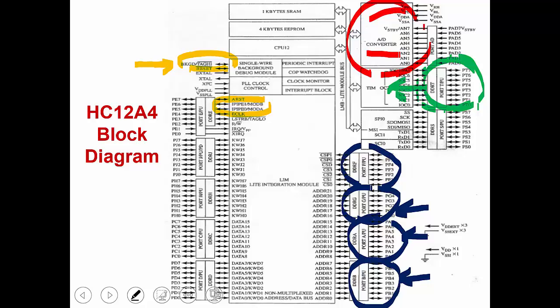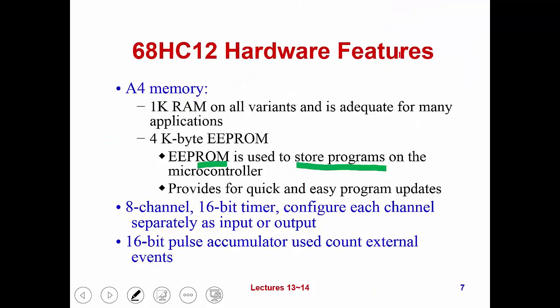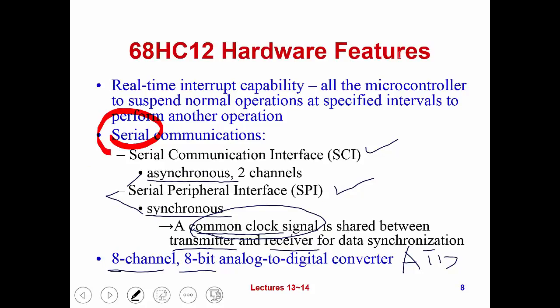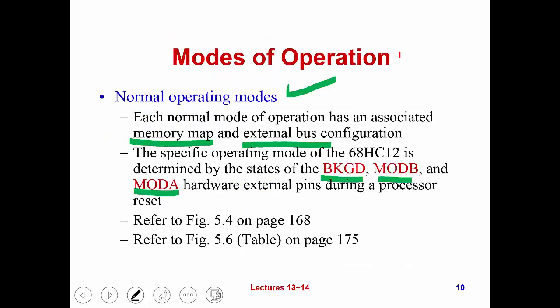That register is called the A to D control 2 register. It's designed to change the setting of the A to D conversion system. We can make the leftmost bit, bit 7, be 1, which will turn on the A to D conversion system. So it's very easy. In this case, we need to store the value 10000000 into this address 0062.